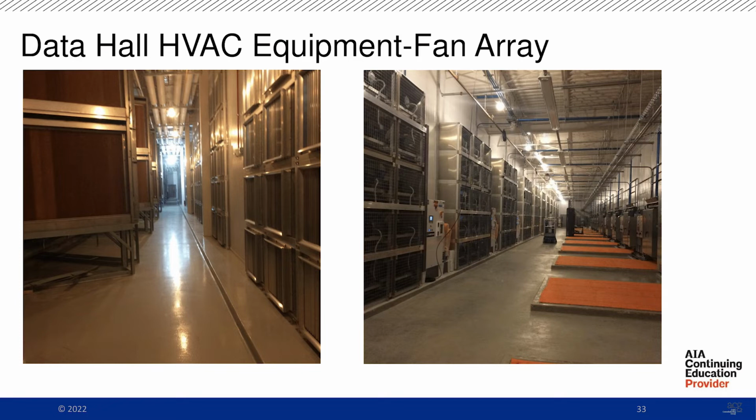Okay, there it goes. What I'd like to draw your attention to here is as the airflow goes into this fan array, down here very low, that's just a wall. There's really not a path for that airflow. It has to simply turn and go in. So the fans down the bottom are already going to be underperforming regardless, because the inlet conditions are a lot different than what we have up here.